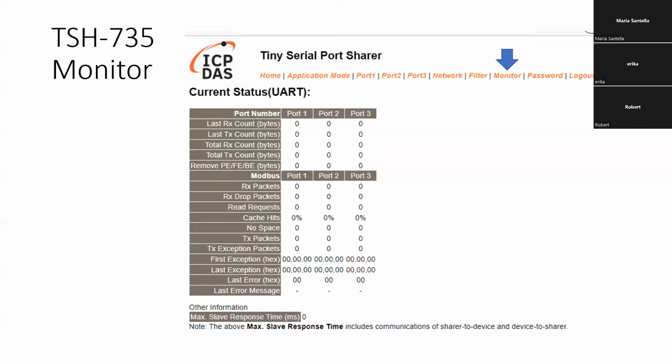If the second master device either polls slowly or the packets are small, it's usually not a problem. But if both PLCs or both master devices are communicating very fast, this may not be the perfect solution for you. So this application works very well for data logging, where data is maybe taken every second or so, or infrequent polling or monitoring from supervisory control.